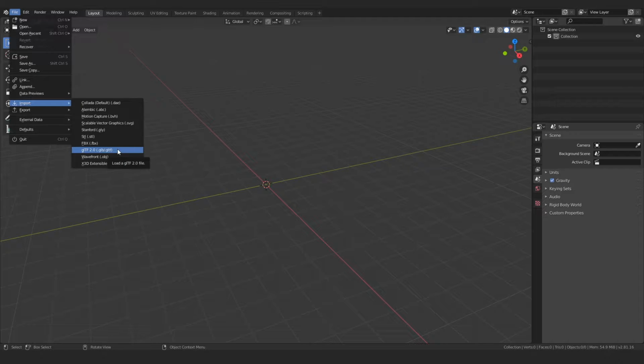I don't think it's perfected quite yet, but the goal is to have glTF include animations and image textures. We have OBJ, which doesn't typically import image textures. For us, fortunately, it will, because Meshroom generates another file called the .mtl. So for whatever format you're using, if you happen to know which file format your photogrammetry software puts out, just find it here.